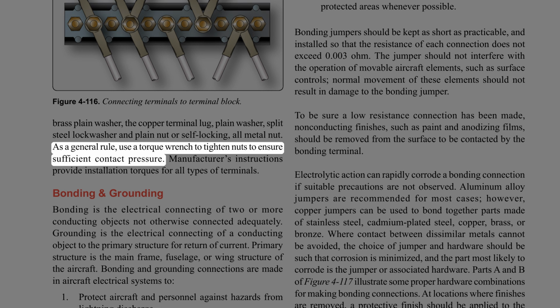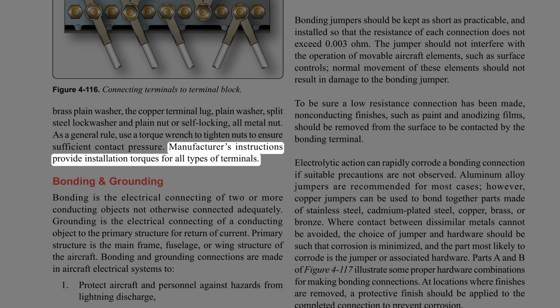As a general rule, use a torque wrench to tighten nuts to ensure sufficient contact pressure. Manufacturer's instructions provide installation torques for all types of terminals.